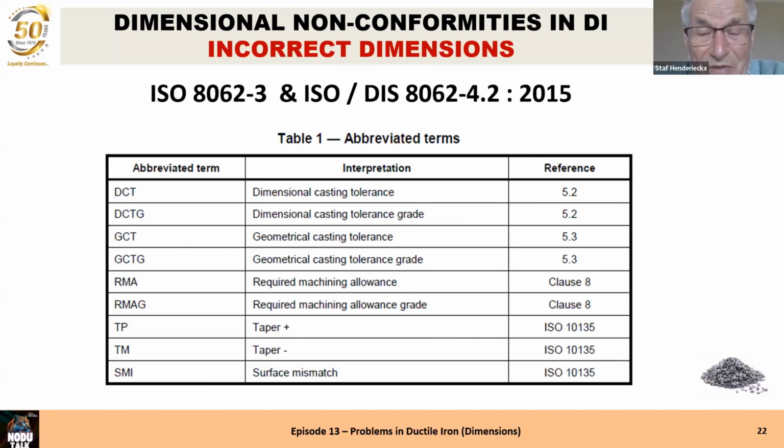Please remember, especially when we have bigger castings, that the top of a casting should always have more machining allowance than the bottom, while all the, let's say, inclusions and everything float up in the casting, especially thicker castings, and therefore we need some more machining allowance.